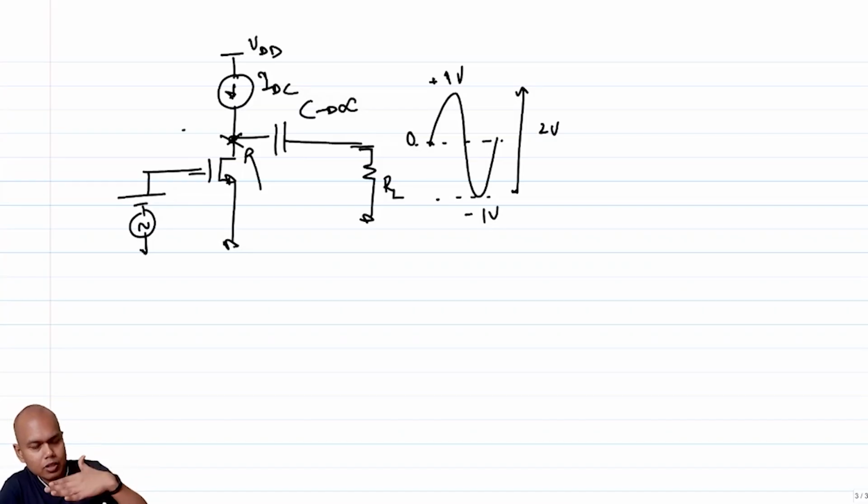If I am talking about the junction capacitance between the gate and the channel, or the PN junction, there is also a junction capacitance, and each of these junctions has a breakdown voltage associated with it, right? If you give too much of an electric field across these junctions, then there can be a punch through of the carriers to the dielectric, and you can have breakdown of the transistors. So which essentially means that you will always have some maximum limits of swing that you can sustain.